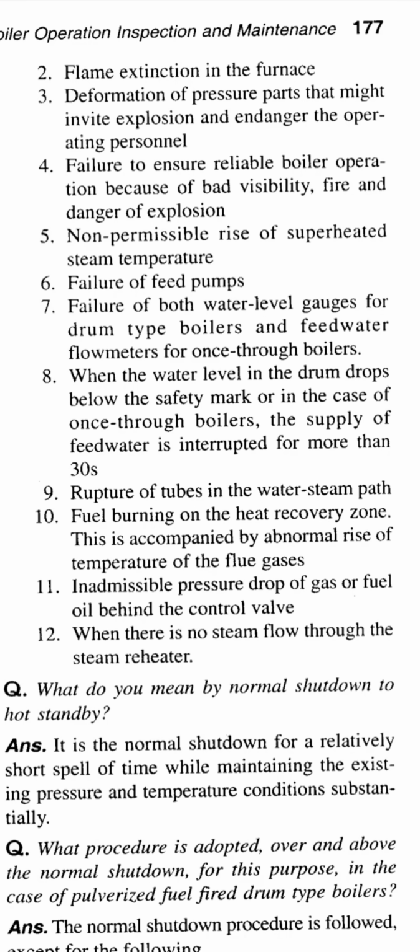Rupture of tubes in the water steam path, fuel burning in the heat recovery zone. This is accompanied by abnormal rise of temperature of the flue gases. Inadmissible pressure drop of gas or fuel oil behind the control valve. When there is no steam flow through the steam reheater.